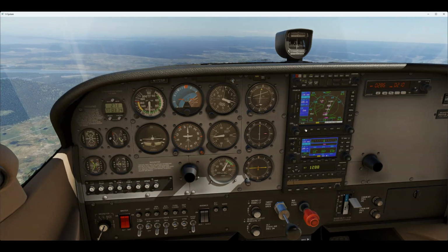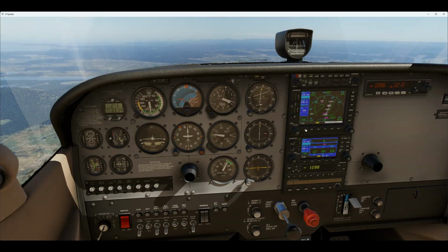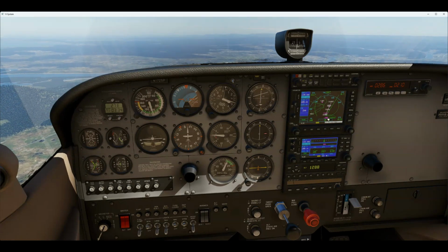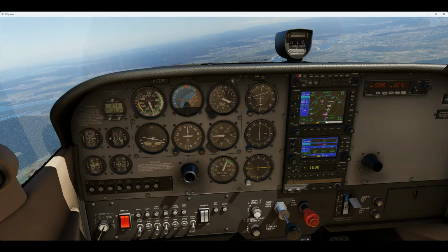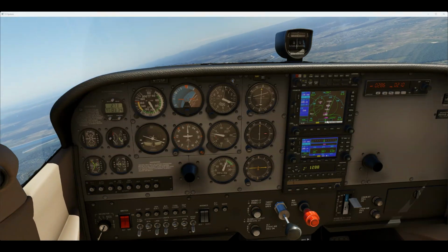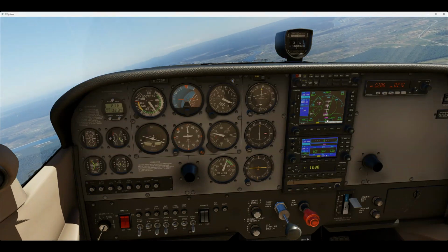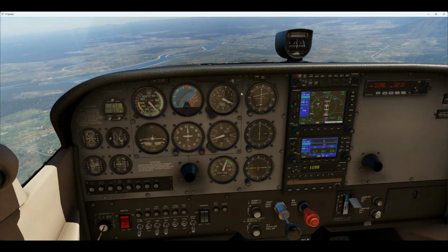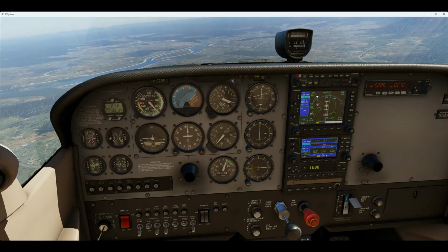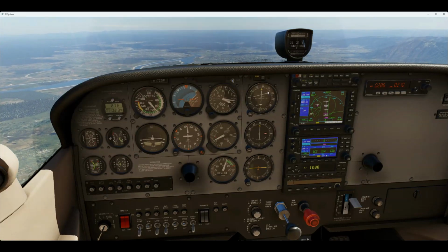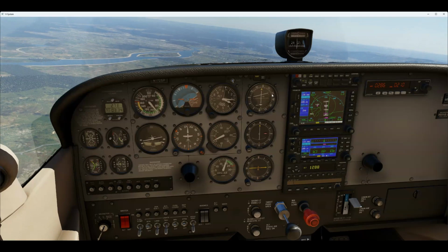The other thing I want to do now is start navigating in VLOC mode, right? As soon as I hit the VLOC, it swapped me over. So this now will be pointing towards the VOR. This will still be on the GPS, which is kind of useful. We want to be tracking a 212. If I'm lined up here, that's great. I want to keep the height up because we haven't got the localizer here. So we want to track 212.